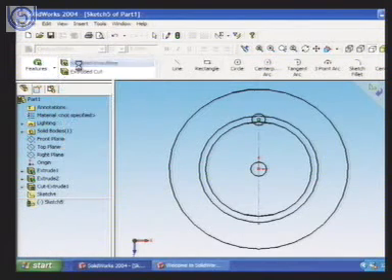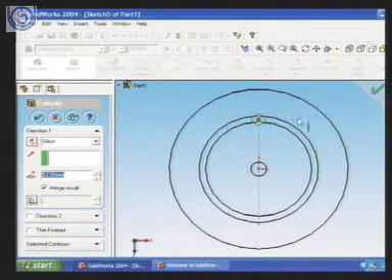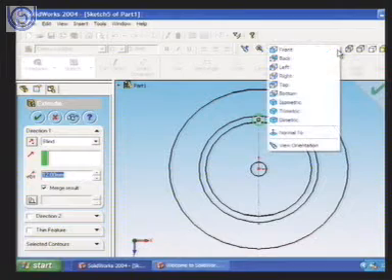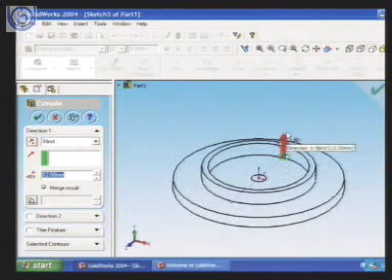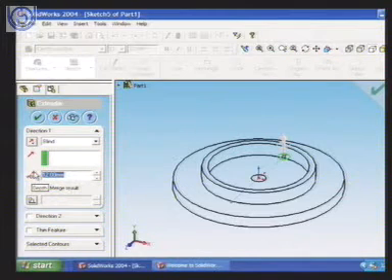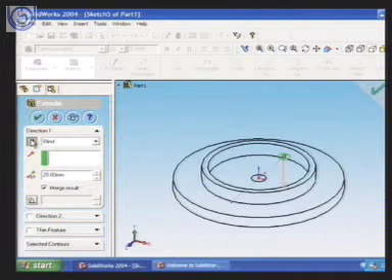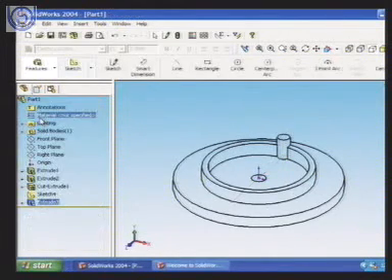I have to extrude the boss. We have to see the trimetric view. It is in this direction and we want it in this direction, and I say this as 20. So if I change the direction, this will be the direction, you can see. So this is what we have created, the boss.